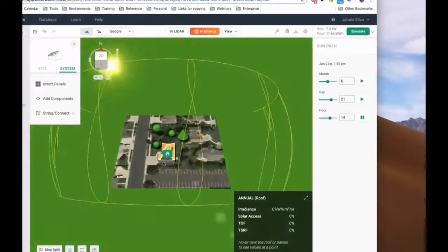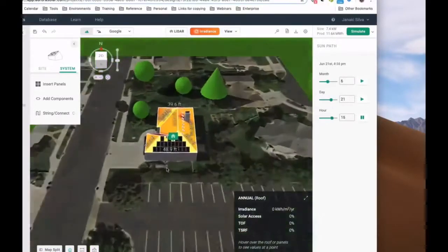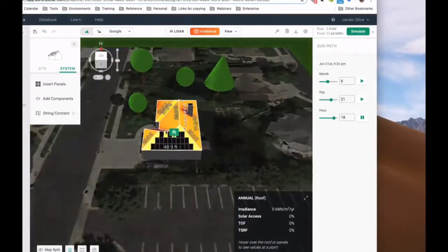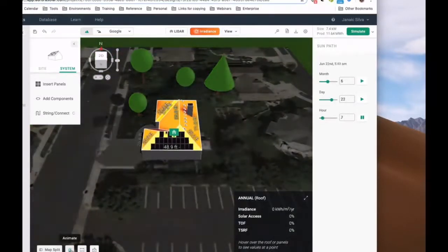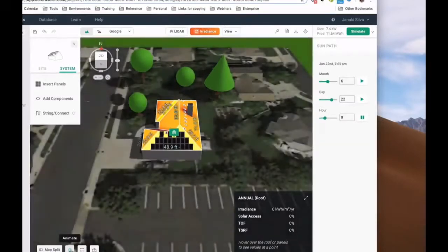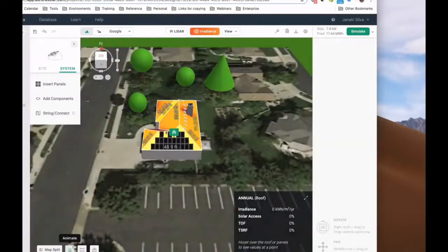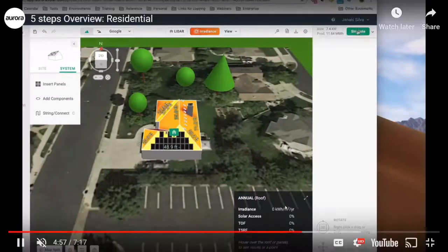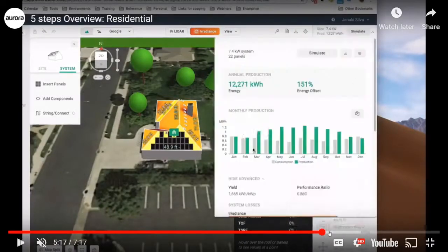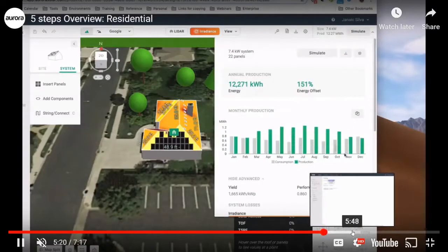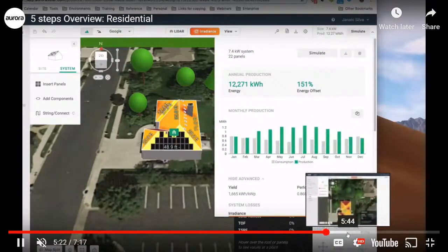Previous examples, they're selecting their module, they're selecting their inverter, and it's doing the string sizing. And because it is truly building a 3D model, it will be calculating the voltage drop for every single panel on the roof. They have a very robust, very strong engine.